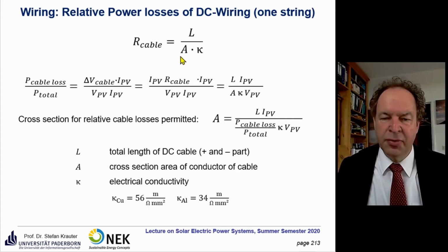So if we put that value in, the square millimeters will be eliminated. You have ohms in the lower part, and the meters will be eliminated by this length, and at the end you have an ohmic value.